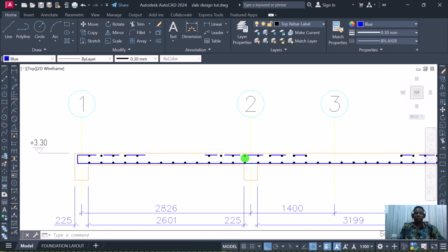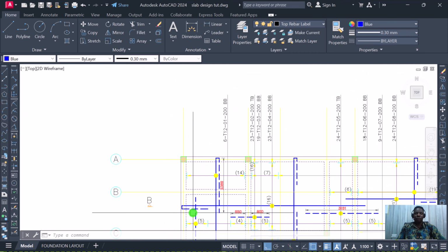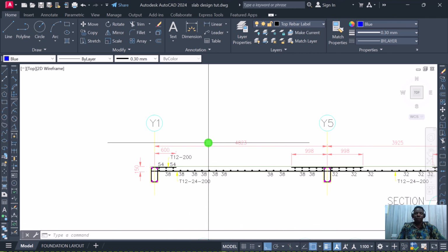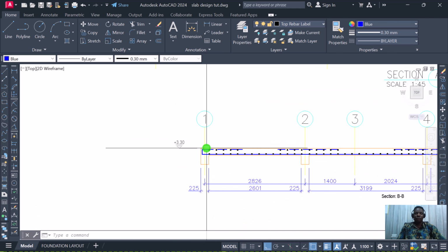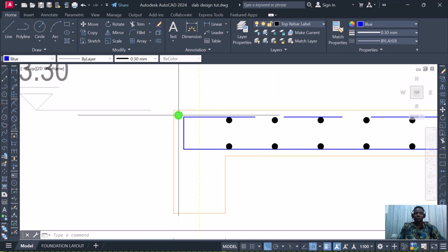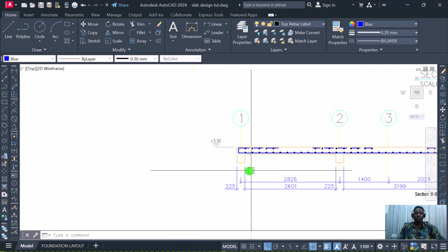So definitely we just have to check the spacing and check how everything, you can see the return. You can see how we put this rebar. This explains what we are going to have over here. This is going to be the bottom rebar. This is going to be the bend along the beam, and we're going to reinforce it down over here. So generally you can see what we have here. We have it on the bottom, and to move up and have a return, it's going to go up. So that's what we have.